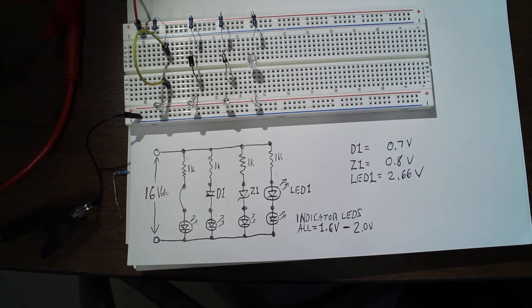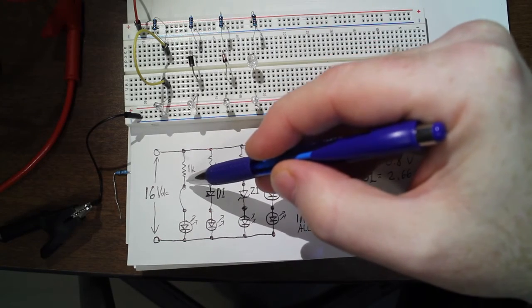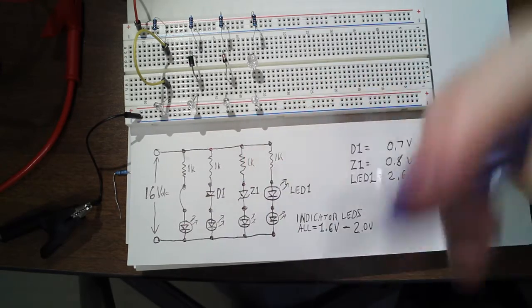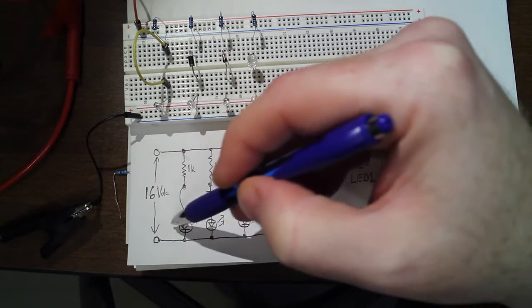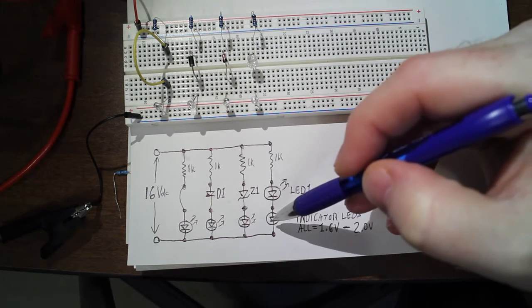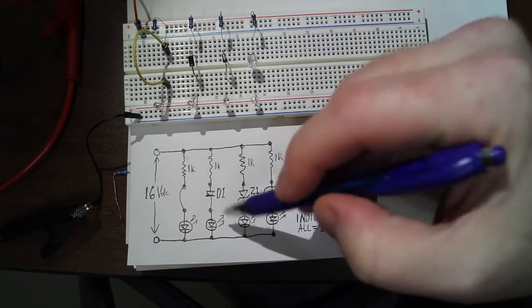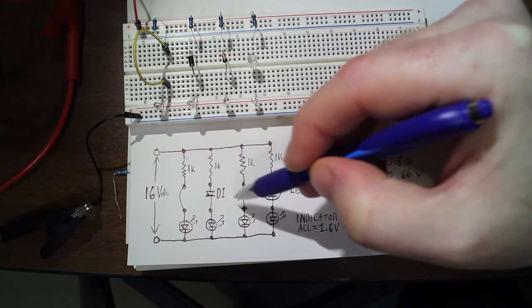Now this circuit that I've built on the board is fairly simple. It's 4 sub-circuits in parallel, each powered by the 16-volt power supply. The first branch is just a 1K current limiting resistor in series with the small red LED, which I'm using as an indicator of current flowing or not. The other 3 branches also have the same indicator LED, which will not light up until a minimum voltage is reached of 1.6 volts. But in addition to the indicator LED, you also have the voltage drop of the diode that is in series with the indicator LED.